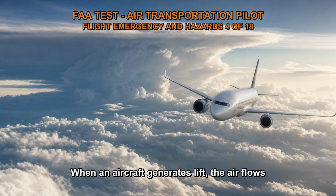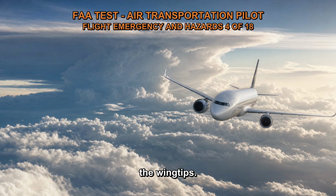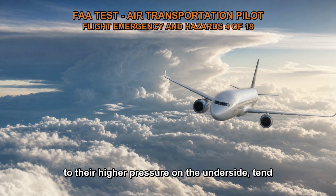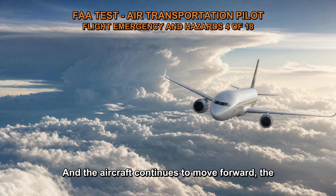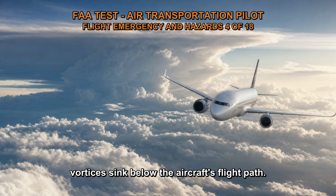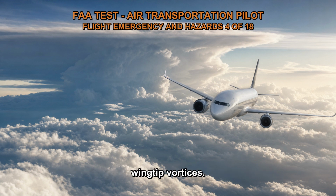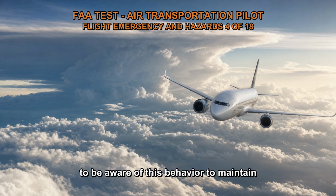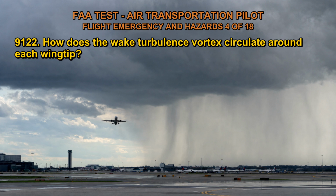When an aircraft generates lift, the air flows over the wings and creates swirling vortices at the wingtips. These vortices have a rotational motion and, due to their higher pressure on the underside, tend to sink downward. As the aircraft continues to move forward, the vortices sink below the aircraft's flight path. This sinking motion is a natural characteristic of wingtip vortices. It is important for pilots of following aircraft to be aware of this behavior to maintain safe separation and avoid encountering the hazardous turbulence created by the vortices.